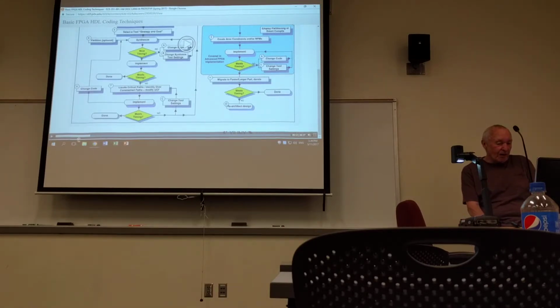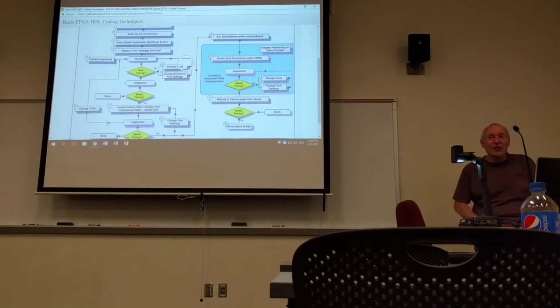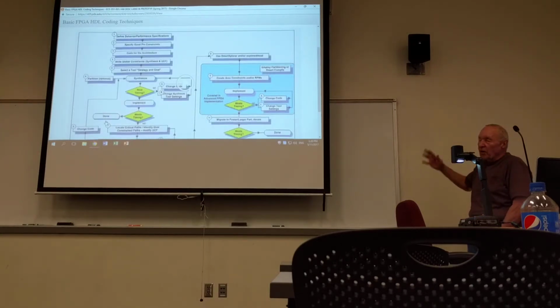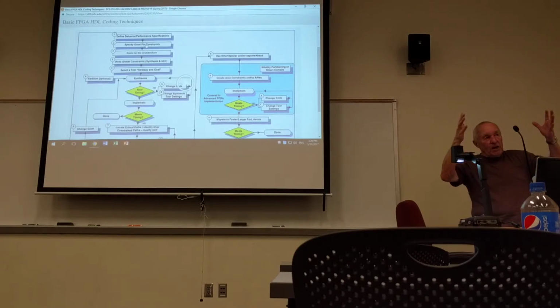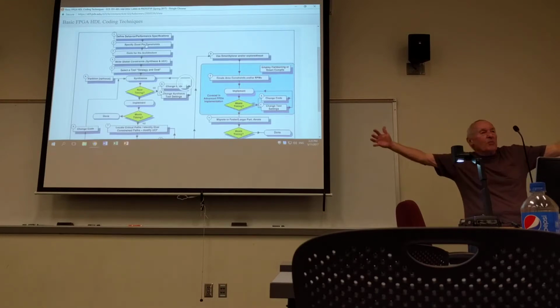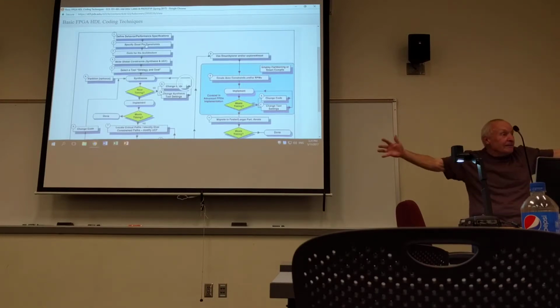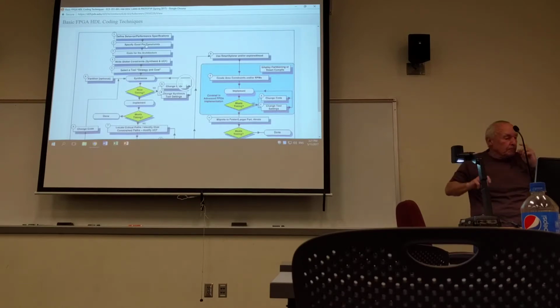Incidentally, this diagram here shows you everything that's involved in creating a design. If you'll notice here, and rather than going through this in detail, I'll go through it very quickly and then we can speed on. You've got your specifications, and you have to determine good pin constraints. When you assign your pins, you don't want to have the inputs necessarily on one side of the chip and the outputs on the other. That's long data paths.